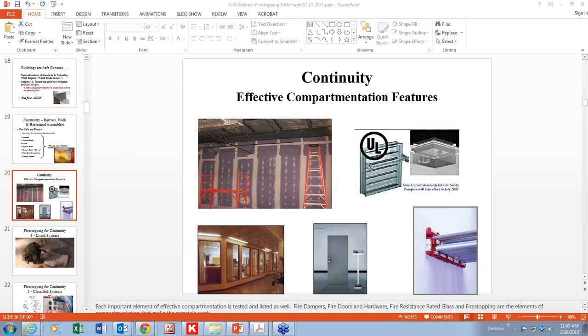The ASTM standard is known as a consensus standard and an industry standard, and that's what's expected as the minimum to get by. So therefore, I would answer the question, yes, an L-rated Firestop is required for a smoke partition.